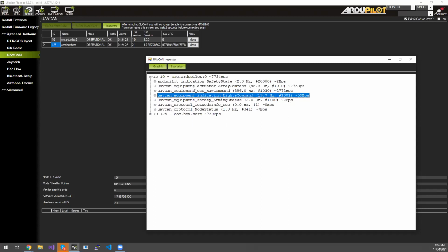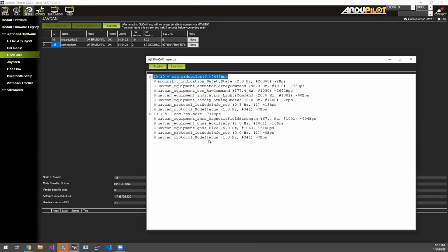One of the other things is the approximate bandwidth on the bus. I will say SLCAN is a very inefficient protocol. So that is the message bandwidth on the bus, not the actual bandwidth on the bus. It'd be getting close to double that by the time you got to the bus, and then possibly double plus a bit for the actual SLCAN packing. Complex subject, and I'll just leave it at that for this point in time.